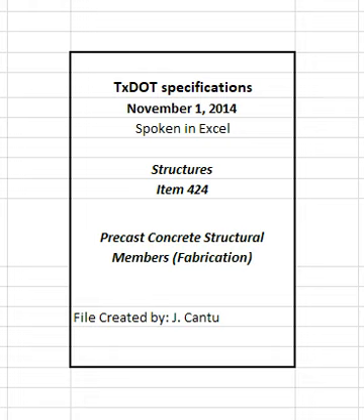Suspend tensioning operations until the problem has been identified and corrected in the event of discrepancies greater than these tolerances. Verify uniform application of load to strands for multiple strand tensioning systems by measuring the movement on opposite sides of the anchorage.